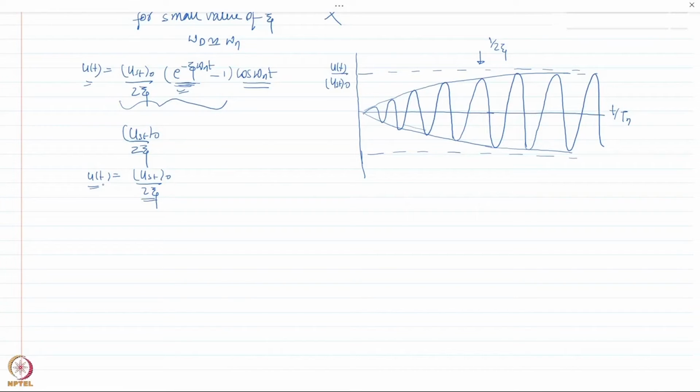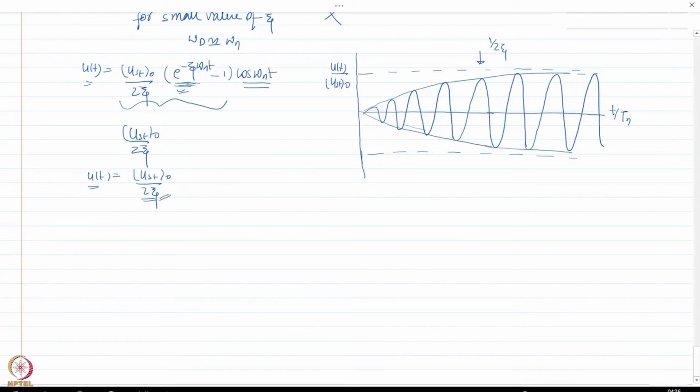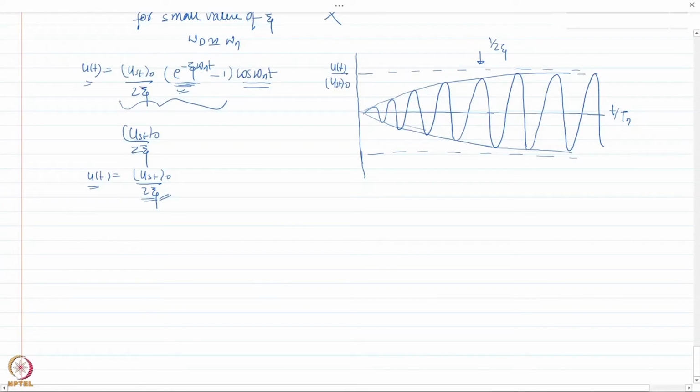There are different types of dampers, but the idea is to provide damping in the system because we might not always be able to predict what kind of frequency the loading might have. Loading could have different frequencies, and even if you anticipate those frequencies, it is always better to take countermeasures and include damping in the system, because if there is damping in the system, then the response will always reduce.